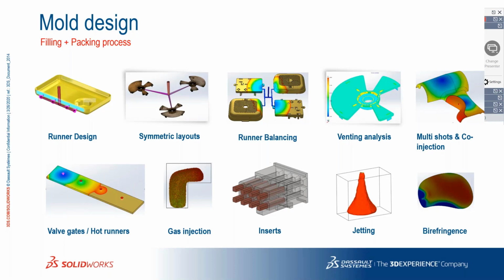Here in the mold designer aspect, what we can have as options in SolidWorks Plastics is runner design and symmetrical layouts, where I have to have the symmetry of filling the multiple cavities, and the balancing of runners as described for different volumes and different parts. Filling time has to be uniform, and there is venting analysis on how to make the vent so that I avoid gas traps or air traps and so on.